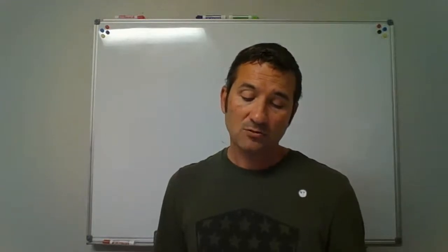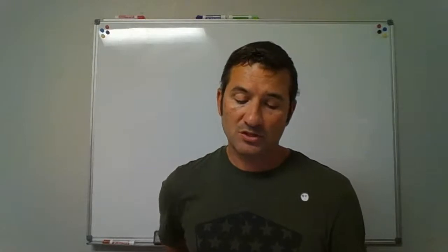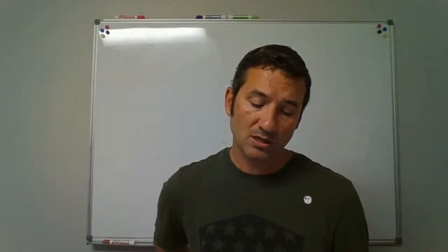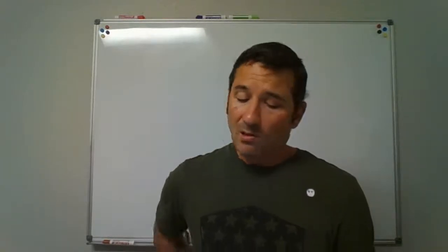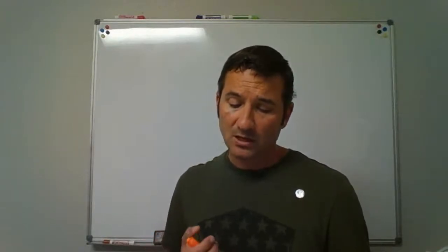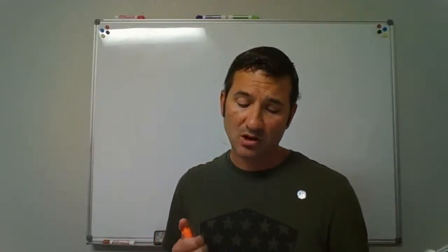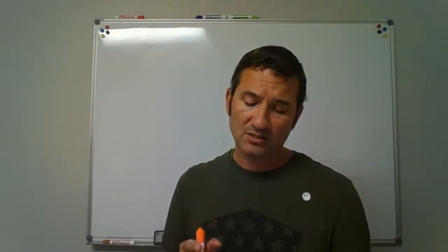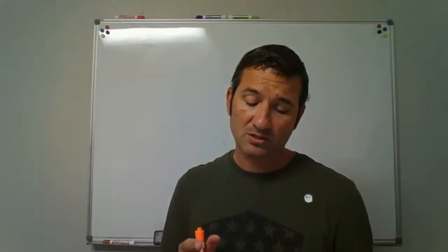Where is hot water required? 607. It says in residential occupancies, any place that you can occupy, hot water shall be supplied to plumbing fixtures and equipment utilized for bathing, washing, culinary purposes, cleansings, laundry, or building maintenance. In non-residential occupancies, hot water may be supplied for culinary purposes, cleansing, laundry, or building maintenance purposes.